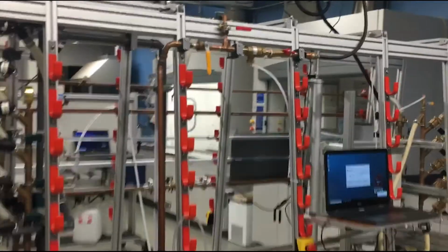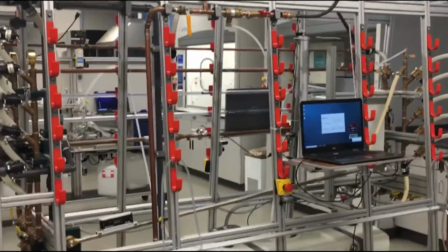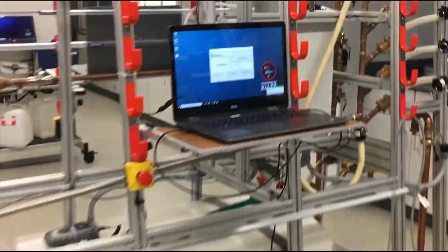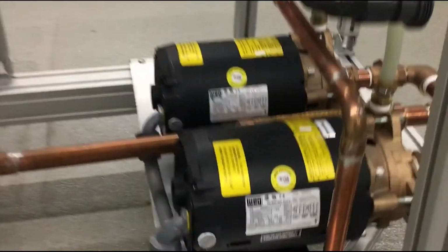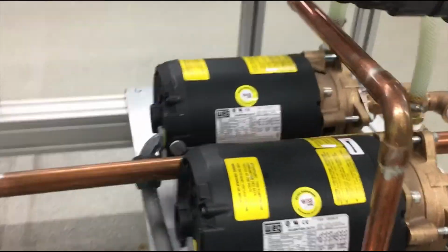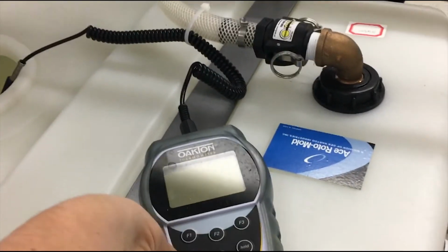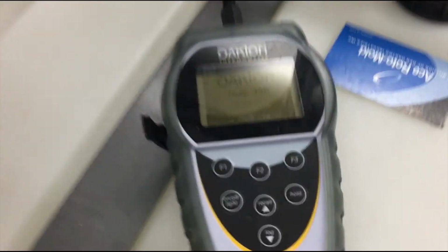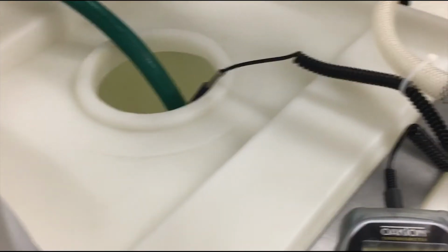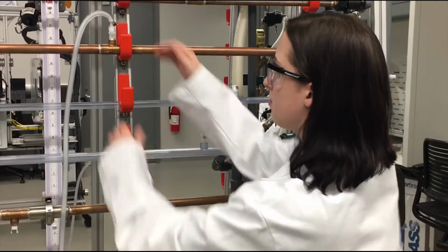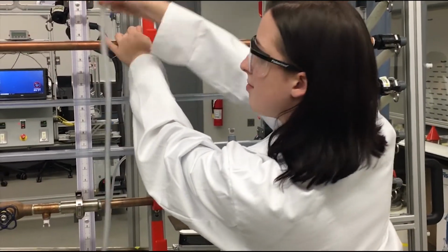Now that safety has been covered, it's time to begin the lab procedure. Start by turning on the computers on both sides of the equipment. While that's preparing, measure the temperature of the water in the tank. This should be done throughout the lab. All of the pipes that will be tested in the experiment should be placed and ready to be used to reduce transitional time losses. To switch out the pipes, 2 people will be needed.